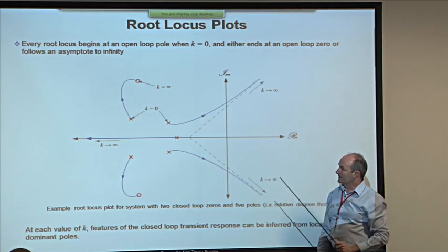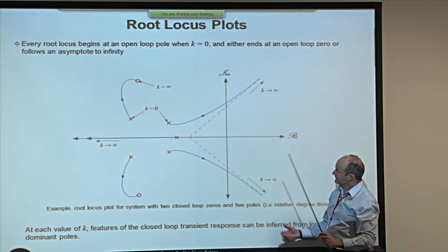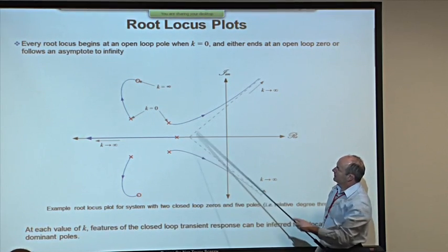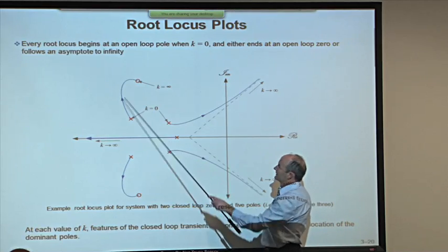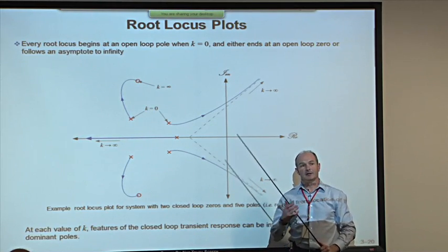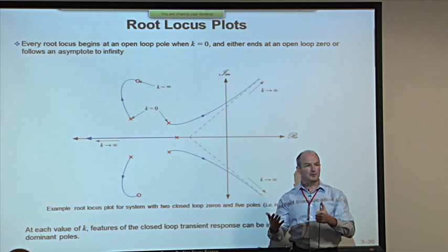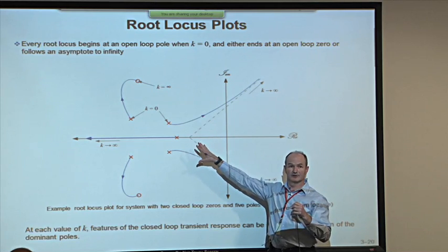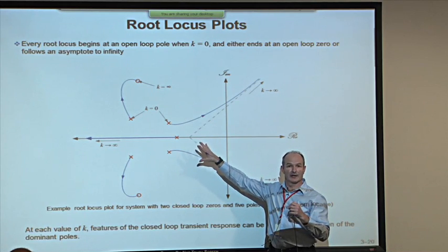Those are called high-gain asymptotes. So can you see that for every value of gain, there is a particular point on the root locus where these 5 closed-loop poles will appear. And the idea behind root locus design is that we infer properties of the transient response from knowledge of how a second-order system would behave for that equivalent pair.